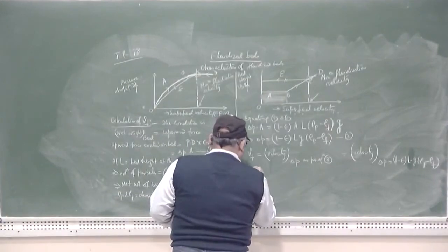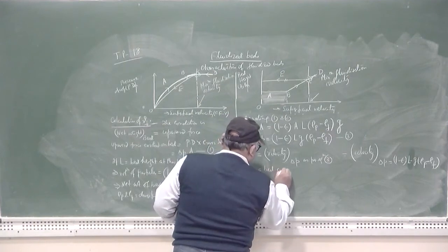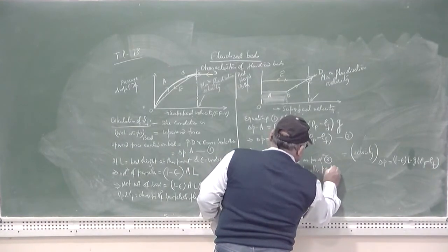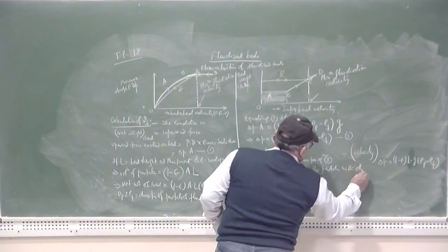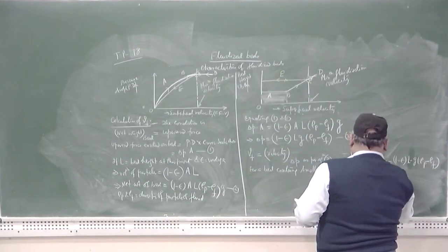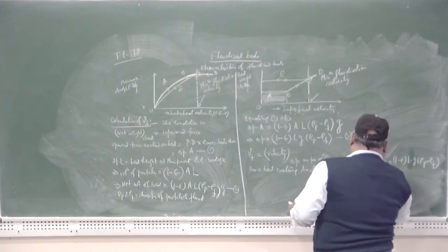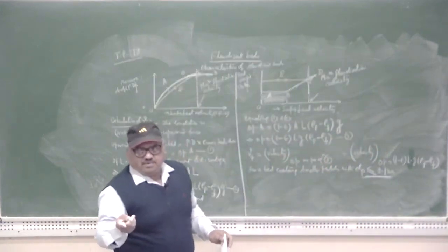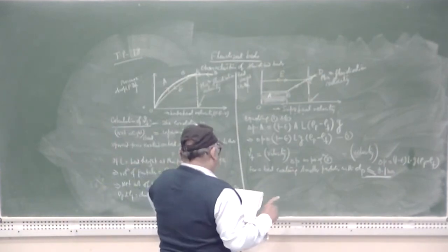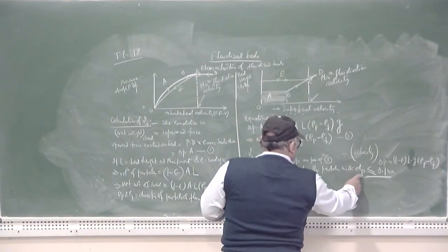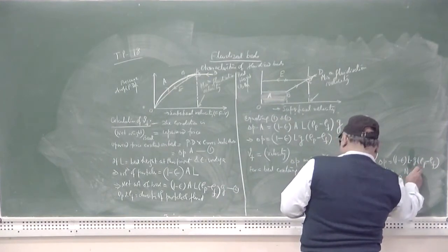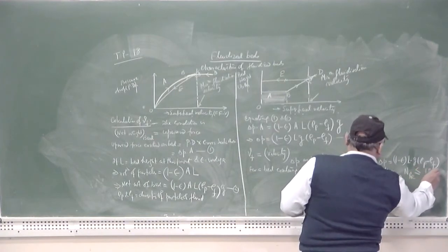For a bed containing smaller particles, with equivalent diameter less than or equal to 0.1 mm, because the diameter has a great role to play in deciding the Reynolds number, which is nothing but the ratio of inertial to viscous force. So when dP is less than 0.1 mm, it means the Reynolds number is lesser than or equal to 10, and